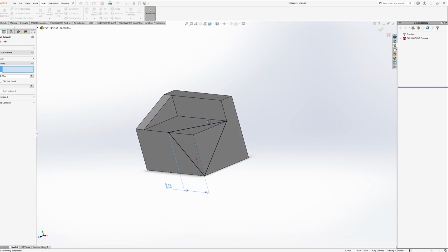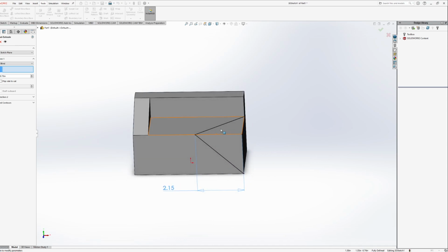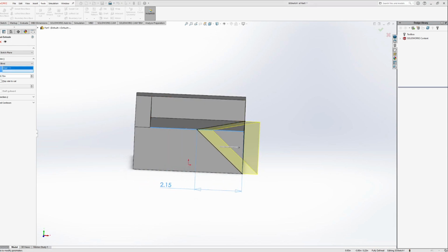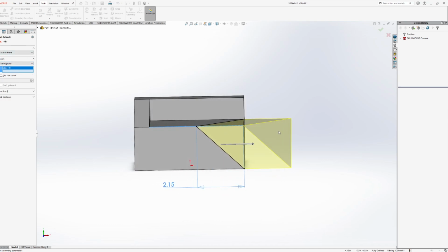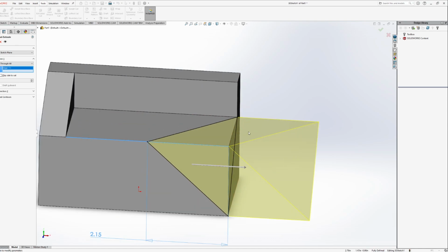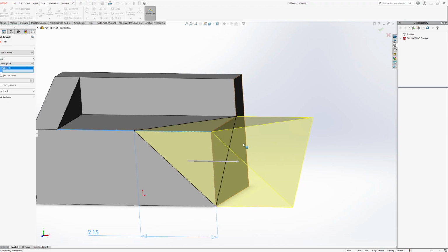Thankfully, most of the directions that we have work pretty much as you would expect. I want to extrude cut it outward to the right. So I'm going to select this edge right here and then just ensure that it's going out an appropriate distance. One manner is I could literally just bump up the distance, but I could also change it to through all. So that means that the lowest point, lowest being used loosely as a term, is going to be on that face of the geometry.